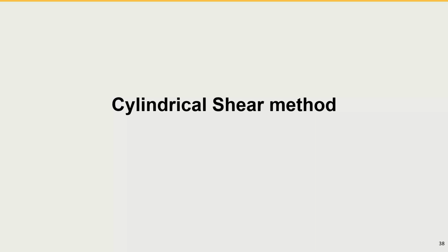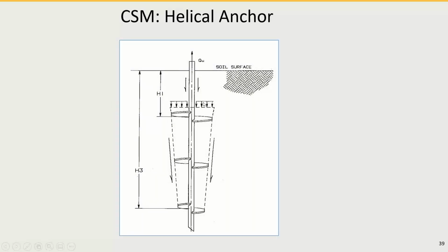Now, there is the cylindrical shear method. The cylindrical shear method, like the individual bearing plate method, is based on traditional soil mechanics. You need the soil parameters to be able to calculate the ultimate pile capacity. This is the same picture as I showed you for the individual bearing plate method.